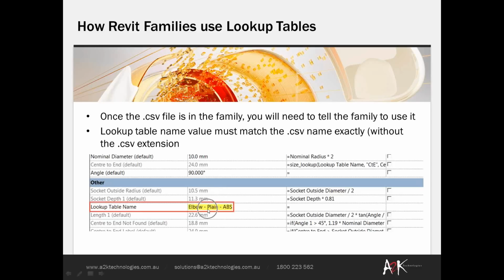One thing that I would suggest: this portion of the exercise is case sensitive, and this other part is not case sensitive. Don't worry, I would suggest you just go by the rule that everything is case sensitive, and whenever you're filling out these things within Revit, try to get the names to match exactly, with spaces, cases, and symbols. Just make sure that they match. That way, you should hopefully never get into trouble. Because I'm sure you're aware that with your formulas in Revit families, you've got to make sure that they are exactly case sensitive and an exact character match of the parameter names themselves. Otherwise it breaks apart and doesn't work. So I would just suggest that.